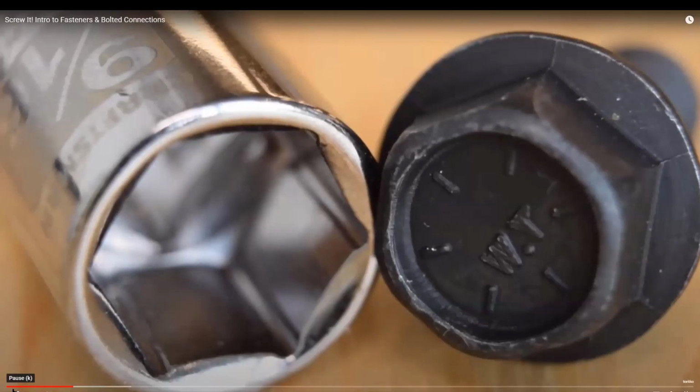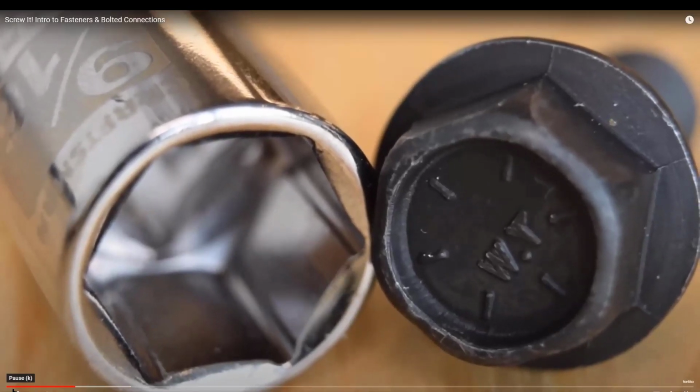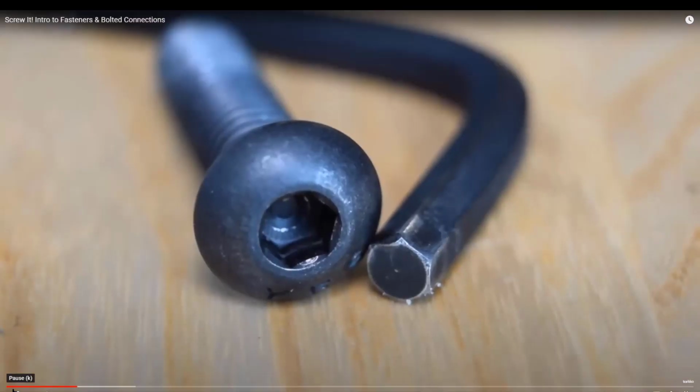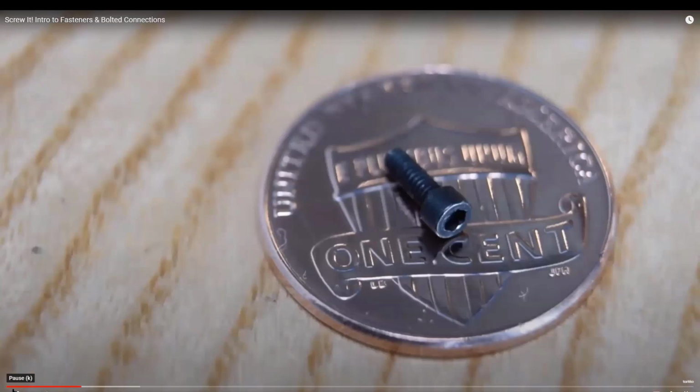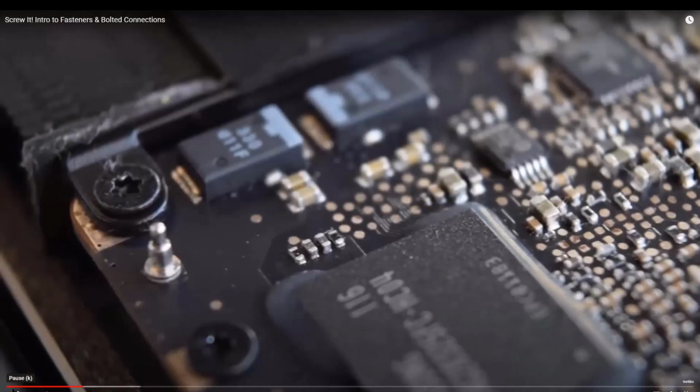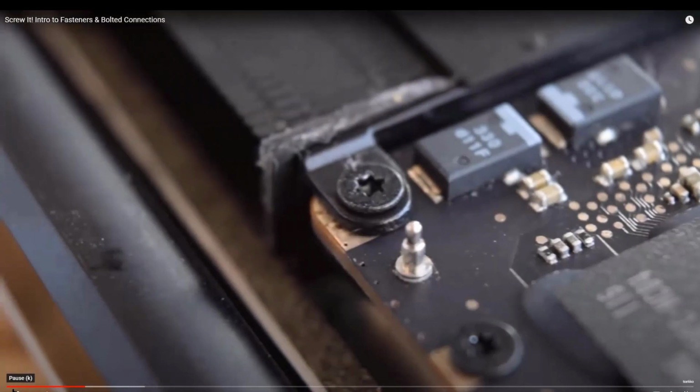Screws are most commonly sold with a hex drive, either external in the case of a hex head cap screw, or internal in the case of socket head cap screws, and this is perfectly fine for larger fasteners. But for smaller fasteners, below maybe a number 6, hex drives strip out very easily, and you should consider a more robust drive like Torx.